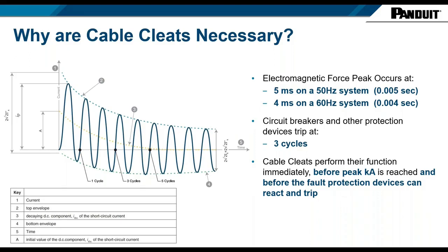You can see after that first peak, we dip below the axis, and then rise back up to the axis. That is one cycle. So on a 50 Hertz system, we get 50 cycles, and at 60 Hertz, we get 60 cycles. So you can see where that one cycle is, and then a bit further along, the 3 cycles, then the 5 cycles, those are cycles or Hertz within that time frame.